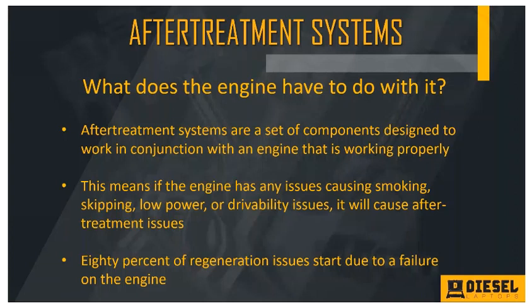So what we see in the field happen quite often is a truck will come in, and the ash load or the soot load will be extremely high in the filter. They'll not really know what to look for, so what they do is they perform a regeneration. I understand. They send the truck out, and then it's back, right? Or maybe the truck comes in and you check it and you say, hey, the ash load's too high, so I need to clean this filter. And then you pull the filter off, you have it serviced, you reassemble it, you run a regeneration, you let it go. And then 3 weeks later, the truck's back. And that's because you never address the root cause of the problems.